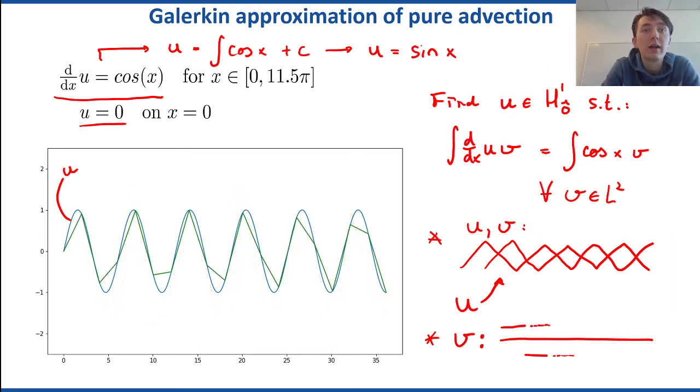That's the green line here. And we see that we get a very good result. Actually, you'll be able to prove that you get these nodally exact solutions. That's not something I want to do, though, in this. Maybe something that we'll get back to towards the end of the class, but for now, I don't think that's important to emphasize. The point, though, being that you do get a very good result now with a method like that. And that is a Petrov-Galerkin method, right? Because we're using a different function space for the test functions and for the trial function.